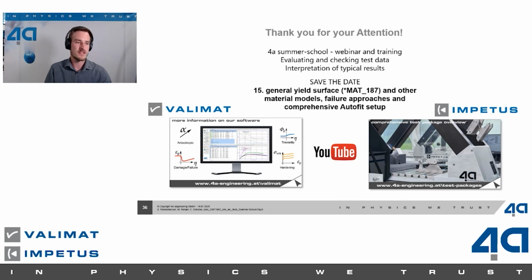So we got a question before the coffee break: what is the maximum traverse distance in the dynamic tensile test? The maximal displacement that we can measure depends on the high-speed camera, I would say, but we can reach much more than 30 millimeters roughly. So we can easily handle 30 millimeter displacement.